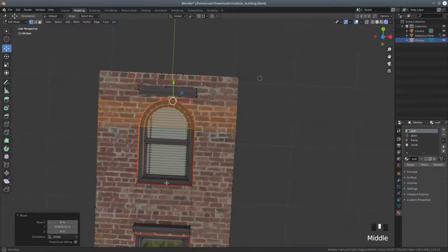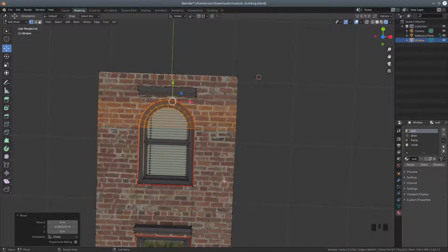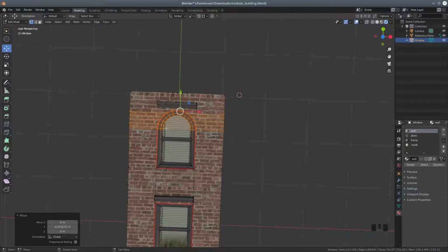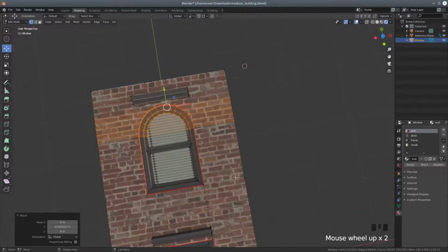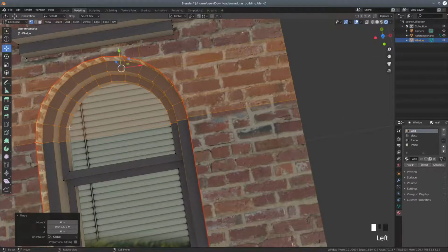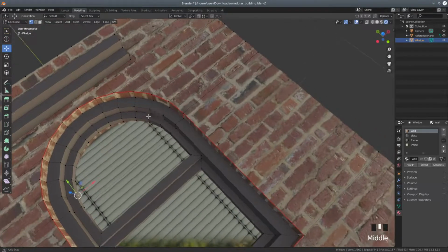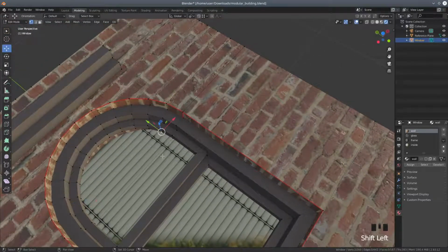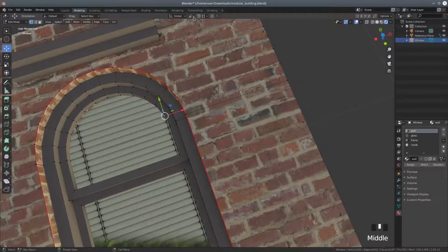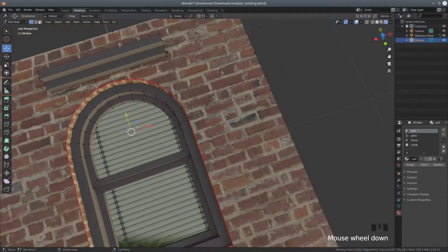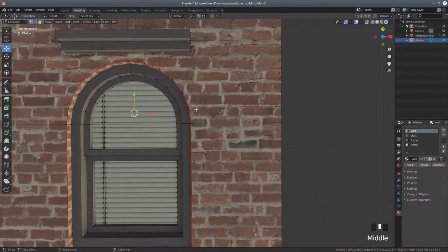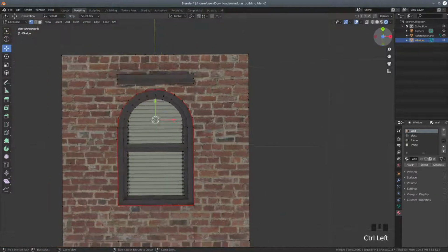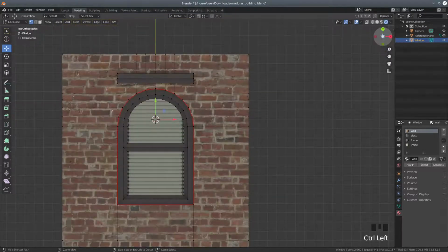select, okay, I don't know where to start that window edge from. Maybe from here, I don't know. So I need to place the 3D cursor. So if I select this vert and this vertices, and I set the cursor to the median point, and I can say Mesh, Snap, Cursor to Selected. Let's just do Control Z again. Oops, should have worked. Control Z, there we go.